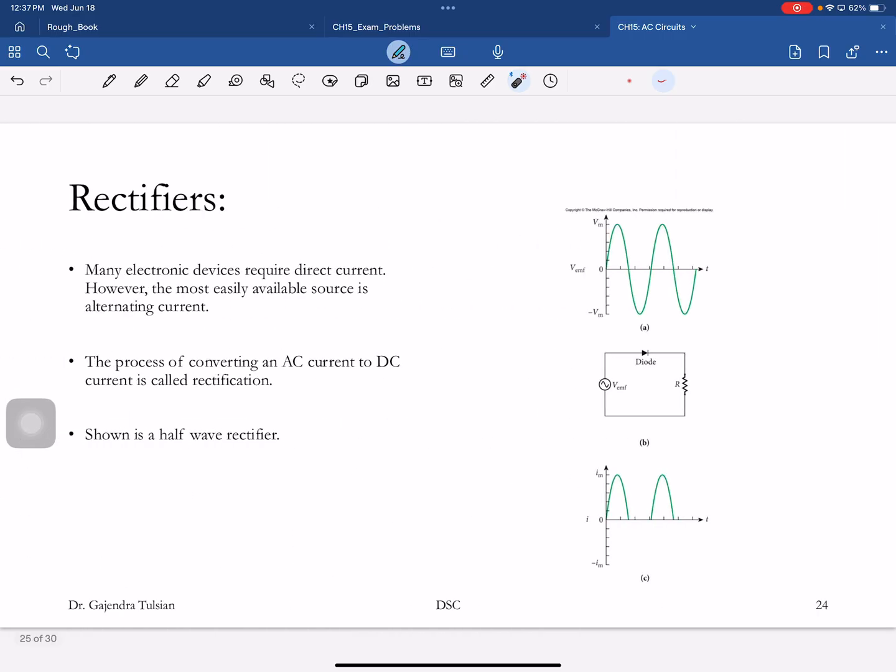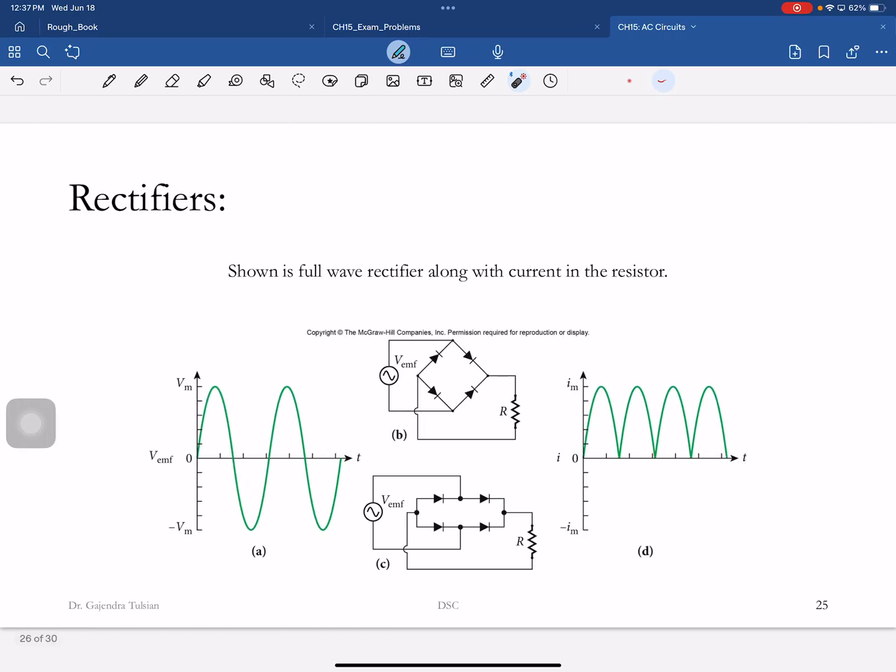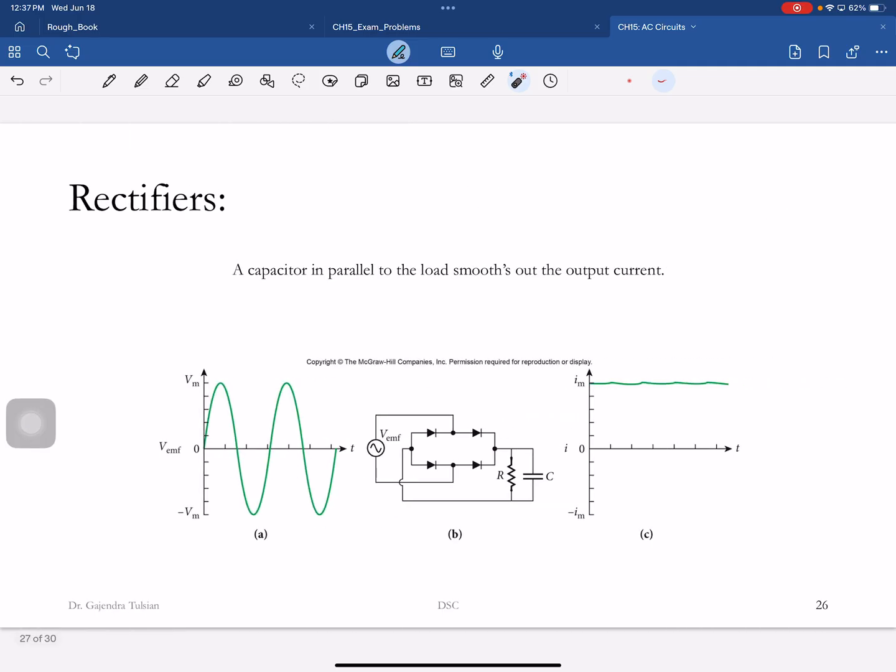So what did you do? Well, you didn't throw away 50% of the money. You got all the money on the table now. But the laptop doesn't like this. You have to smooth it out. So what you do is put a capacitor there, and now if you measure the voltage across it, you get a smooth curve like that. Now this is a simplification, but those are the main elements. So that's what's in the brick.